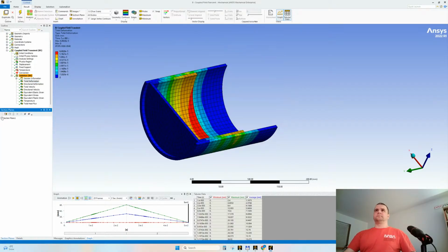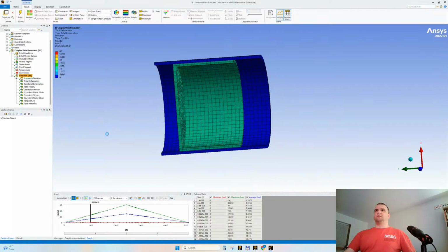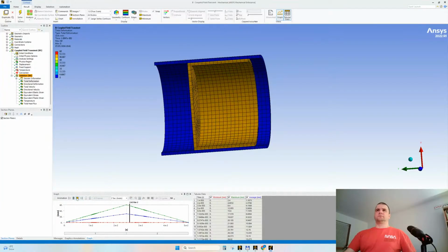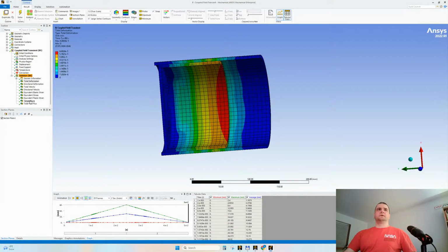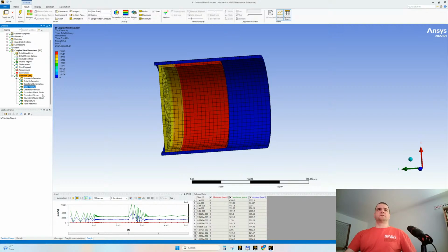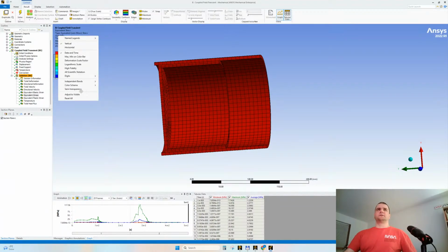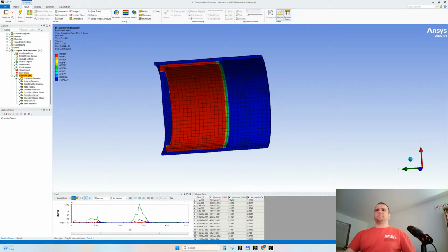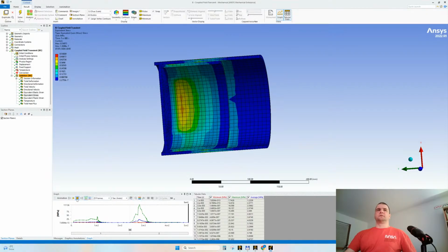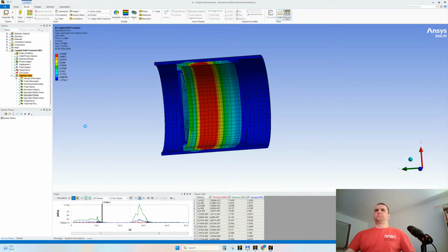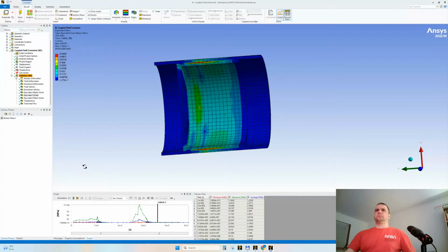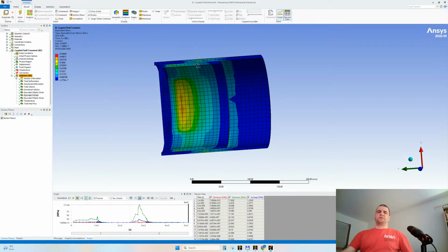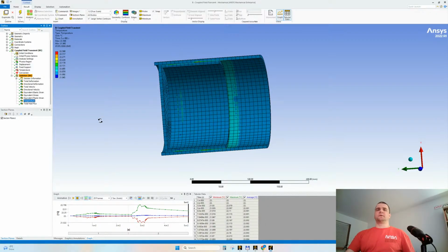Let's see in section what it does. All right, 1 cycle, let's say, all right. I'm not interested in velocity, I'm interested in stress. For example, something like this. Let's click update contour range at each animation frame. Yes. And because we have such transference of stress due to friction, then we surely will have some temperature.